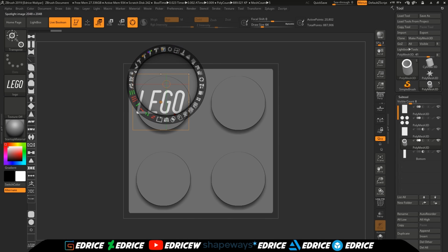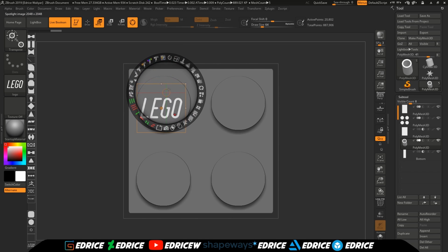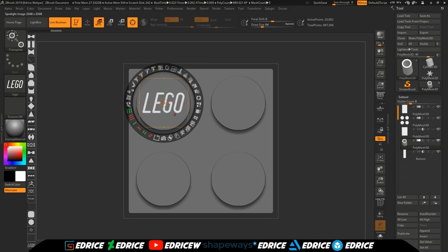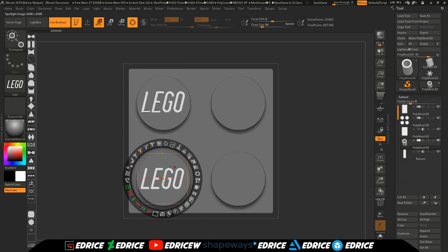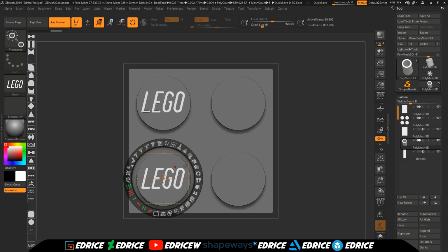Now we're going to scale it to this cylinder thing on top. We're going to hit union. So it drops down, and now we're going to start moving it. And since we cannot mirror it because it will flip the logo, as we are moving down, we are going to hold Shift.